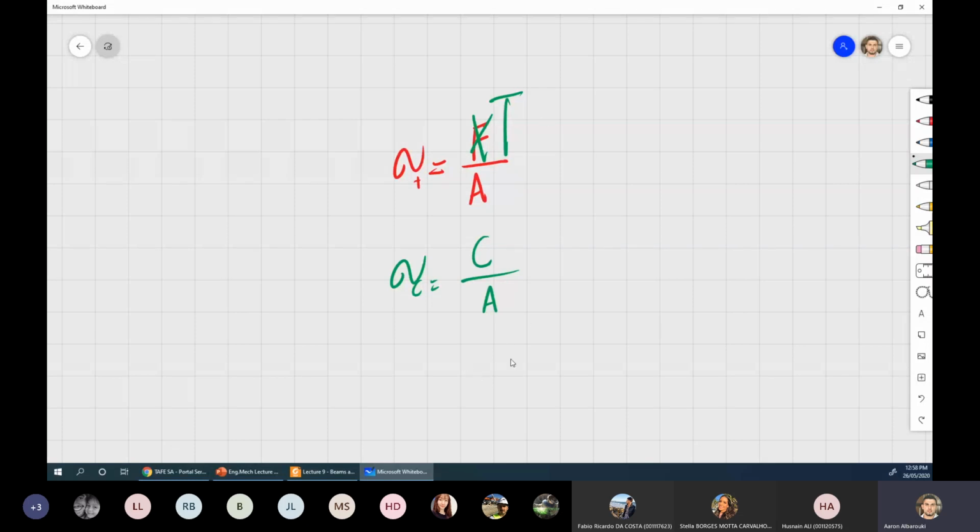So just to give you an understanding of what's going on here, when we're talking about 32 MPa concrete, that's what you hear from people: what strength of concrete you're using. They simply say 32 MPa. They take a block of concrete, usually circular in cross section, always better to test a circular one, and they compress it with a certain force.